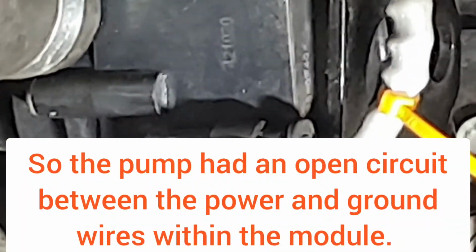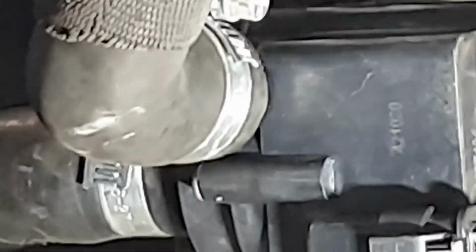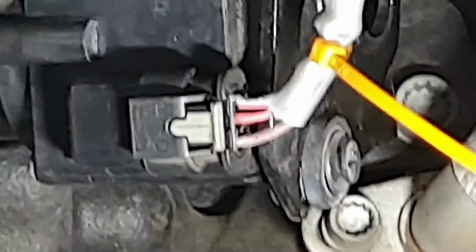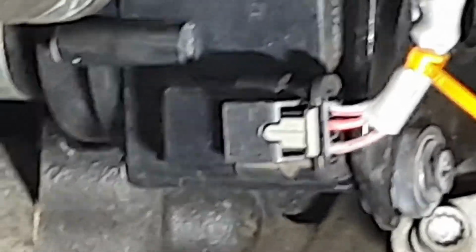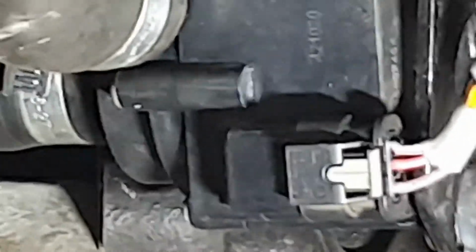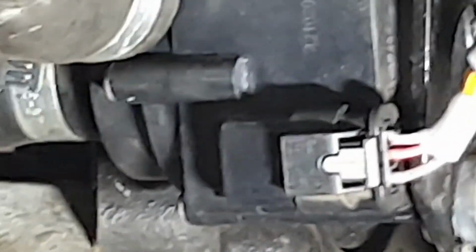So now I suspect, from the measurement I took this morning, the electric coolant pump. When I contacted the garage, they said this is genuine, but it's not at all genuine. I couldn't find any mark on it, like an Audi mark, or any other brand which supplies OEM parts. I couldn't find any, and I suspect the pump is going to be faulty.